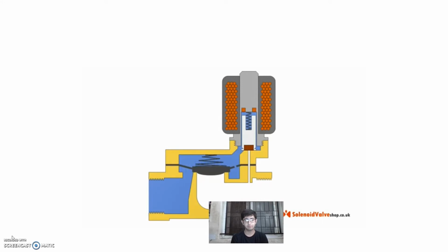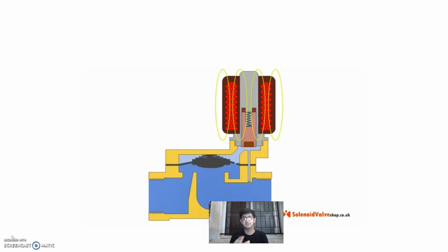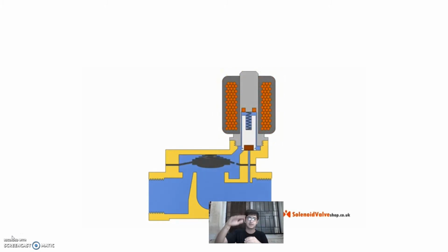Now the fluid will flow through it. This will get energized. Yeah, see, that's the electric coil or solenoid which will get energized. See, the fluid comes out. You can see the wave shown in the animation by blue color. And as the pressure difference is created, the fluid has come out and the diaphragm has lifted.